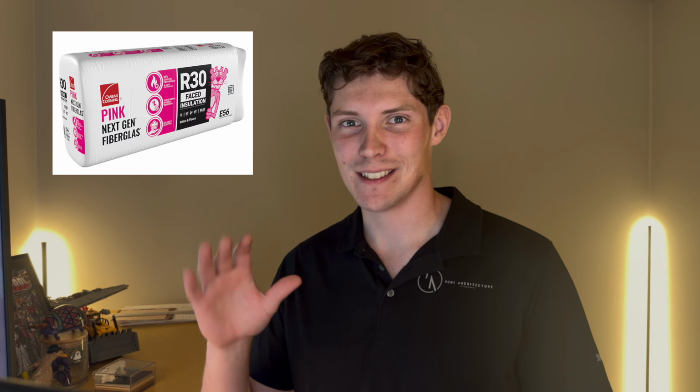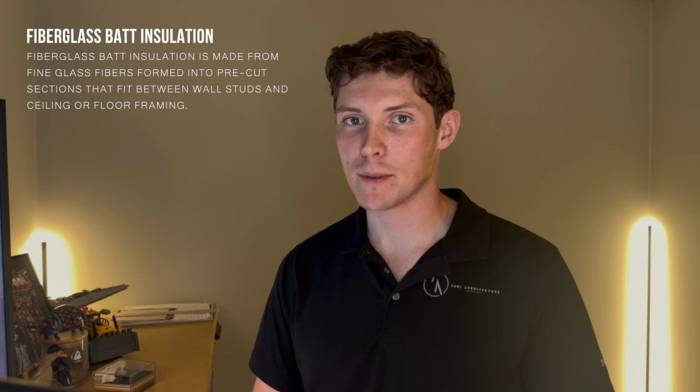Specifically for New York State, the energy code has adopted R30 insulation for your cavities on the interior. Now, if you don't know what that means, when you go to Home Depot, you go to Lowe's, you see those big rolls of fiberglass, those pink things with the Pink Panther on them. Those are your fiberglass batt insulation. So that typically is R21 for a new cavity wall. And with the new code updates, that is bumped up to R30, which, if you guessed, is not on those shelves. So what they have on there instead is you're gonna have to have other provisions.